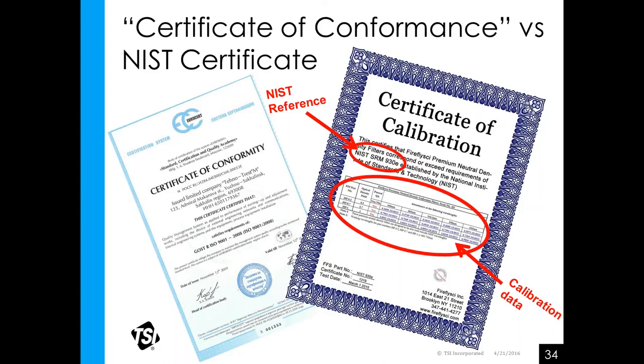So the certificate of calibration may or may not include adjustment data, but at a minimum, it must show as found and as left data. Meaning, the as left data is how it left the laboratory, after any adjustments made to the instrument upon receipt, which are the as found measurements.